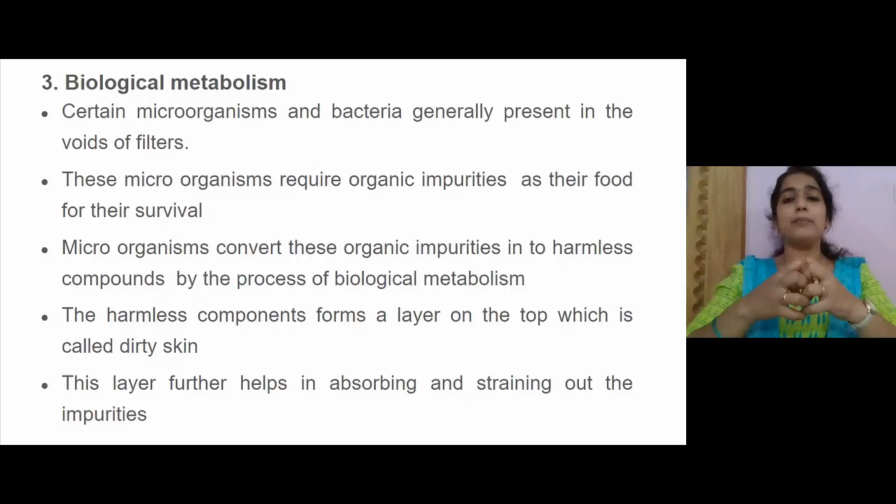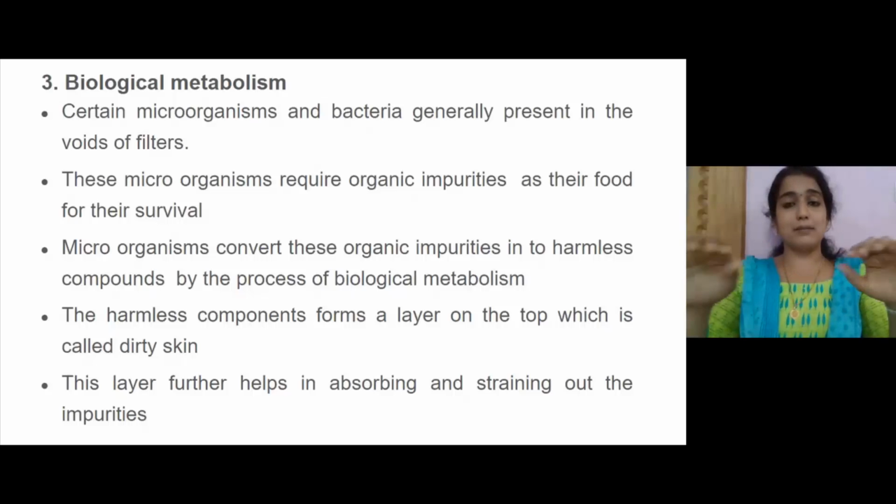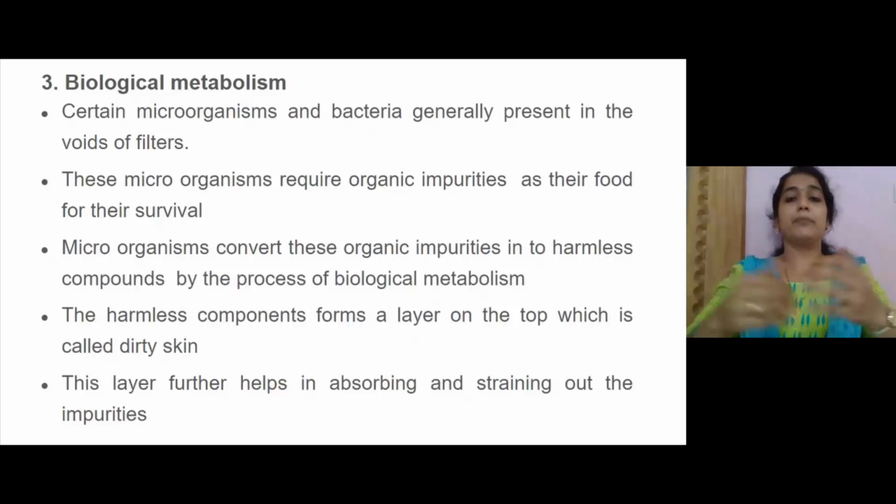They take food from the organic impurities present in the effluent water and convert these organic impurities into harmless substances or harmless chemicals. And these harmless chemicals form a dirty skin, that is a layer of harmless substance on the top of the sand filter media. This dirty skin will support or enhance the filtration process. This is the third mechanism, that is biological metabolism.